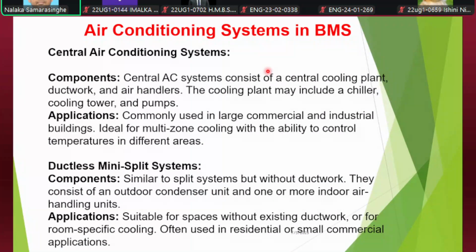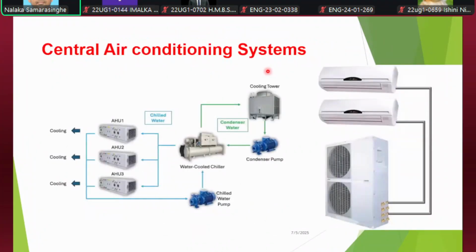And also we have ductless mini split type systems. This is quite similar to a normal split type air conditioning unit, but the difference is, as you can see in the image here, we have two indoor units connected to the same outdoor unit.